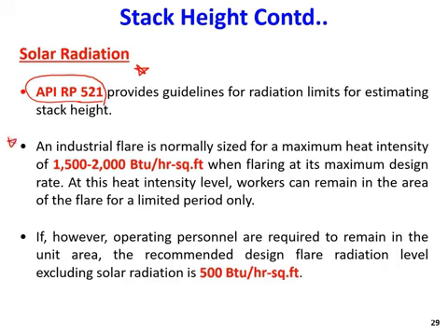This slide in general is important. Industrial flares are usually designed to handle a heat capacity of 1500 to 2000 BTU per hour per square foot. This is the heat value of the gas that they have to flare. So it's usually between this maximum capacity, and we will design the flare to handle this maximum capacity.